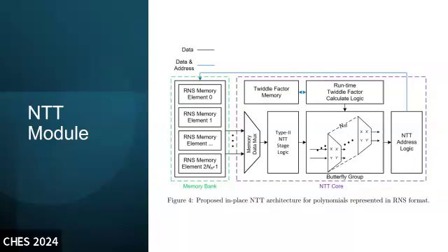As long as we put all the coefficients in these memory bank elements, the whole entity can be operated in a scalable way, executed between different parameters. As long as we don't need to change the memory access pattern, we don't need to change the other logic units, as long as all the memory elements are pre-stored there. Plus this is an in-place NTT architecture, so once the result is calculated, the final result will be in place in the respective memory banks or elements.